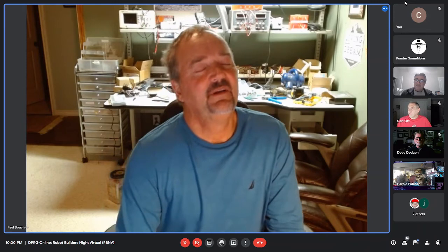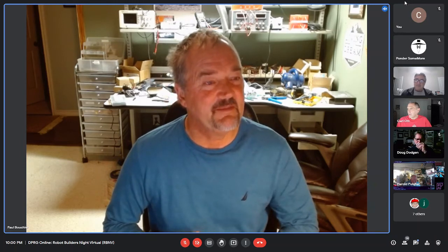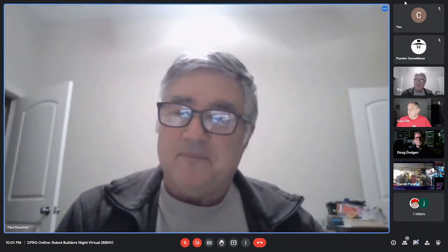Yeah. I mean, with Mobot, I'm not trying to charge it, so it's pretty simple. I'm not trying to charge it while it's running. Actually, that's not true. I am charging it. I do charge it while it's running. But the charger has enough oomph to drive the load once the BMS disconnects the battery. So yeah, it works for me, but I'm saying it may not work in every case for all types of loads, all types of charging currents. Yep, scenarios. Yep. Yeah.